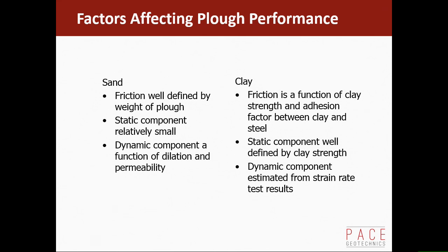The plough performance is affected significantly by the seabed soils. If we take the various components, in sands and clays, we've got a frictional value effectively, which is actually reasonably well defined in most cases. We then have a static component.